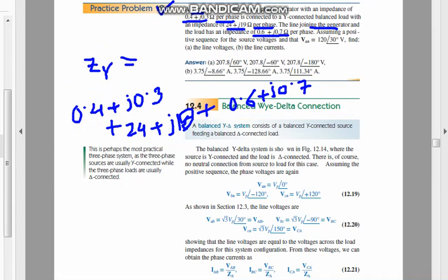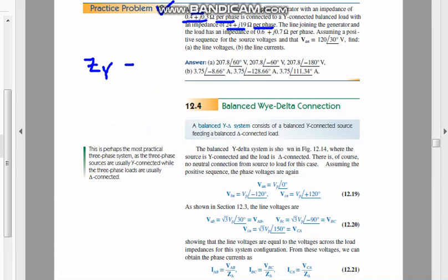Okay, now coming back to the point that we are assuming a positive sequence. Positive sequence means ABC sequence, A, B and C sequence. So you have to go on top and find out what the positive sequence states. As you can see here, the positive sequence is like that: VAN, VBN, VCN. VAN is at 0, VBN will be minus 120 and VCN will be plus 120. That is the positive sequence you have to keep in mind while calculating.